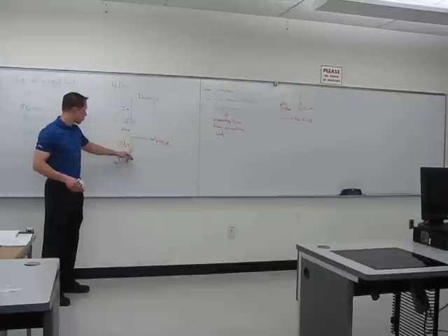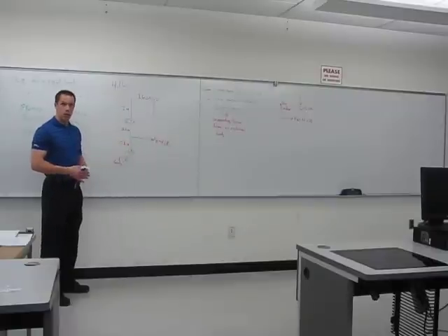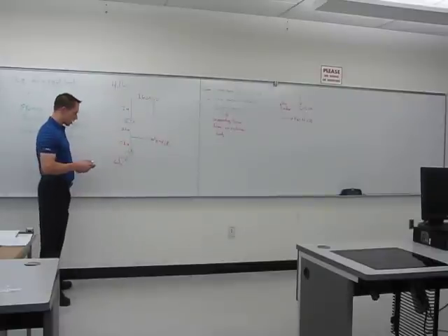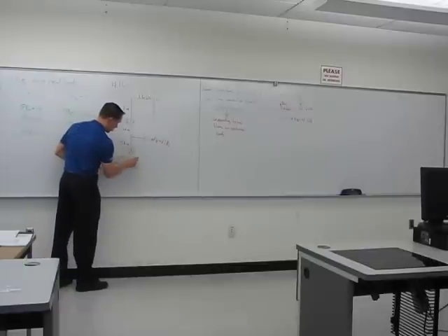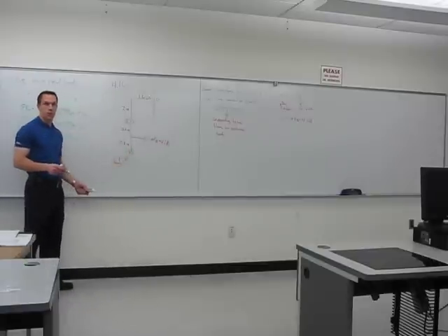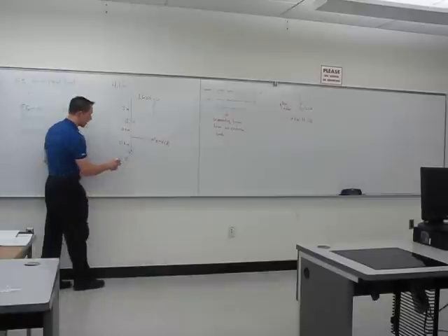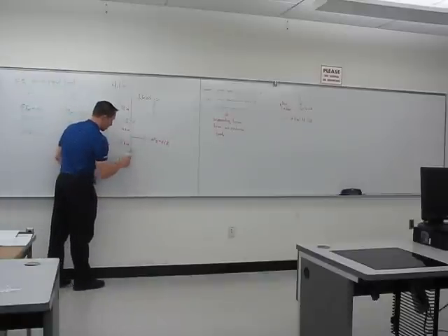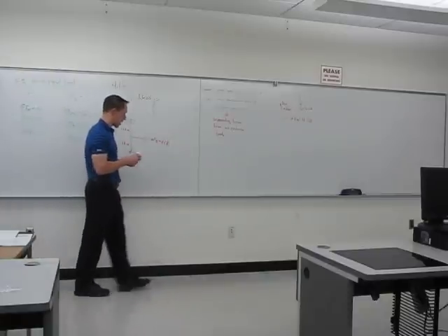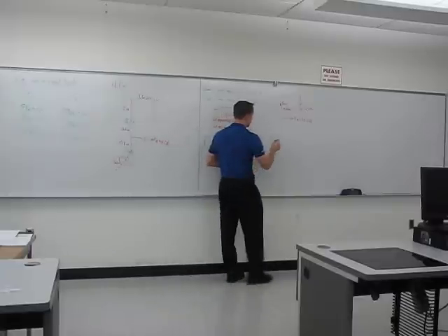So here we've got the two wheels that are in contact. So their common tangent line would be this one. The reaction force is going to have to be perpendicular to that tangent line, which would be the line that we see right here.